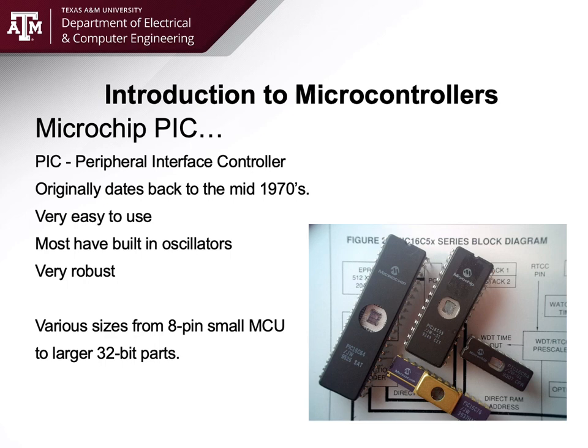So if you ever looked into an old computer, if you were ever kind of nostalgic, looking at like 8-Bit Guy on YouTube or anything like that, you'll notice a lot of the early day processors, like your Color Computer 2 or your Commodore 64, a lot of the ROMs on those boards for those old 8-bit and 16-bit computers, even your early IBM PCs, all had a little piece of tape over the ROM. Well, that tape went over the quartz window to prevent UV light from entering the quartz window and erasing the ROM. So they're very easy to use, still very popular today.